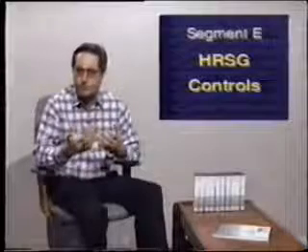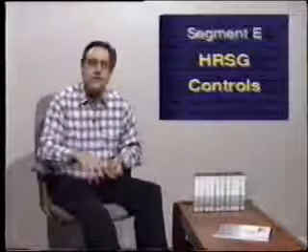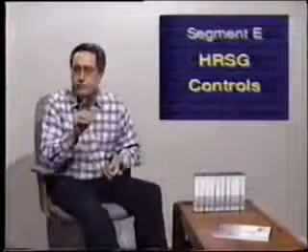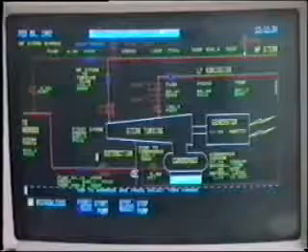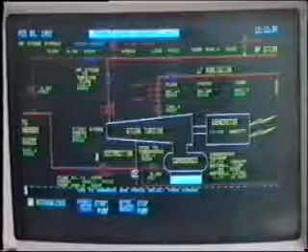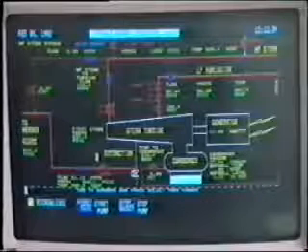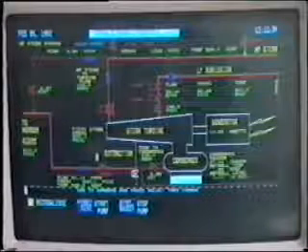If the steam temperature is lower than rated value, then the steam turbine efficiency will decrease considerably. By contrast, if the steam temperature is higher than rated value by, say, 50 degrees Fahrenheit or 30 degrees Celsius, then internal turbine damage will eventually take place. The operator should always keep his eyes on the performance of the steam temperature control system and be prepared to take manual action if necessary.